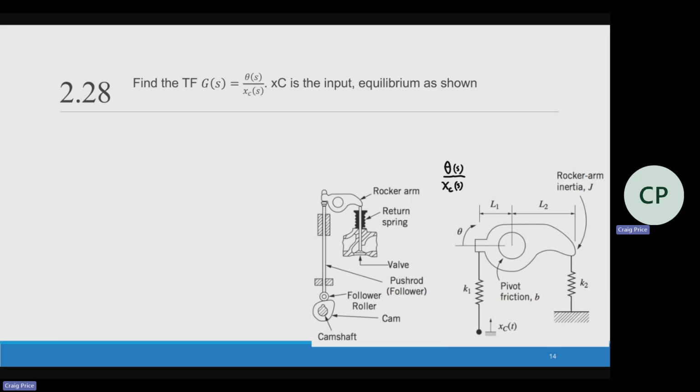So we have a displacement that's an input, not a force. That goes through the spring, and then turns the rocker arm. So, what is the order of this system? It is second order. All I've got is one body. The rocker arm is the only body we're worried about. So it's going to have a theta double dot. We're going to do a sum of torques for this problem. So you want to draw your body diagram. And we know what our input and output is. After that, it's just trying to define it and go from there. So if you have questions, let me know.